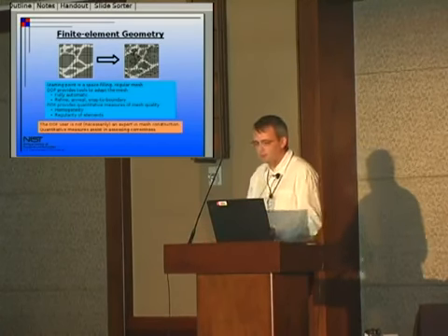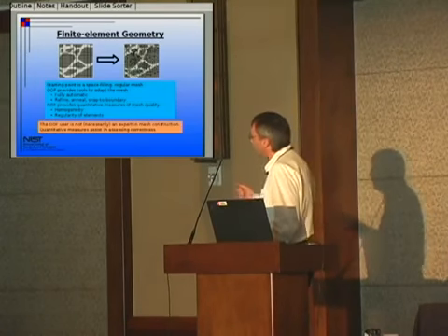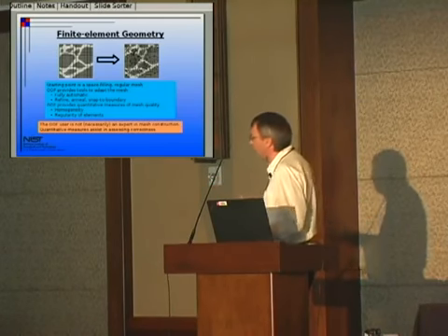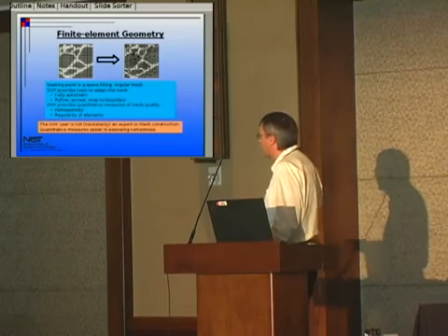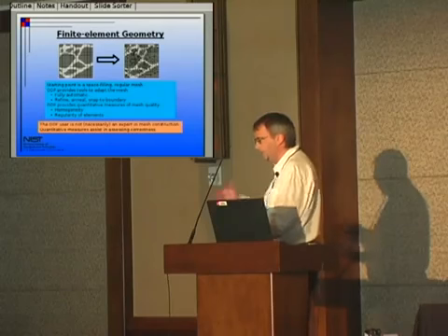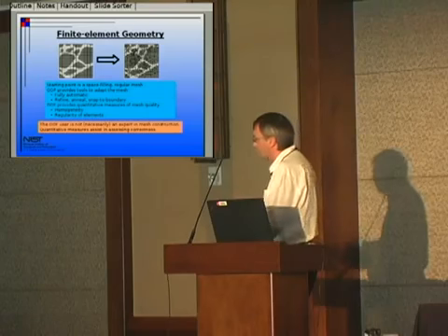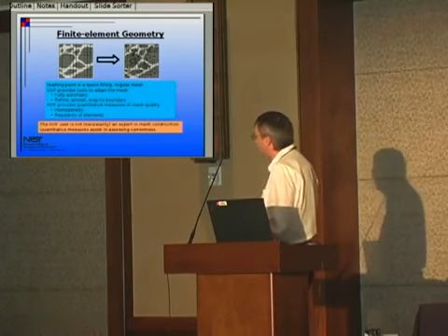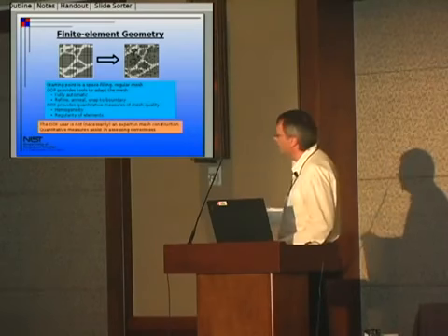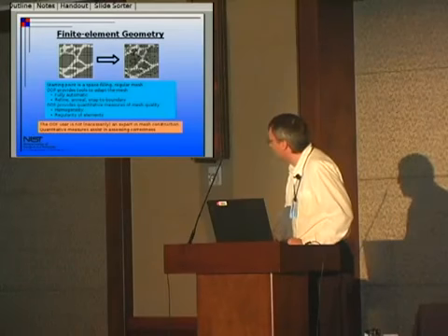So the primary thing is we have a de facto artificial energy function that will tell you there's an energy penalty for elements that are too long and skinny, that have bad aspect ratios, because those screw up the finite element convergence, and there's an energy penalty for elements which are inhomogeneous. If the material boundary goes right through an element, then that means that the skeleton or the mesh is not matching up with the segmented image. And so again, in this case, the user is not expected to be an expert in meshing, but we give them the tools so that they can assess the meshes reasonably well.